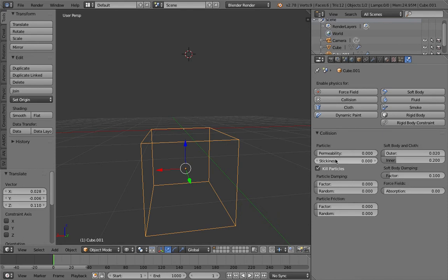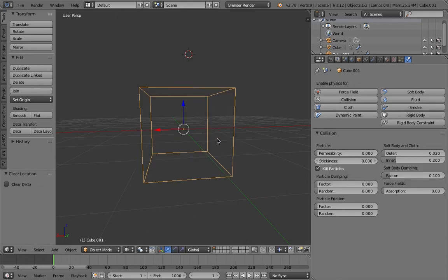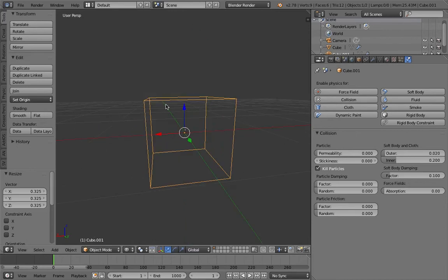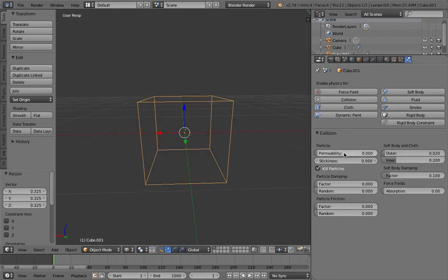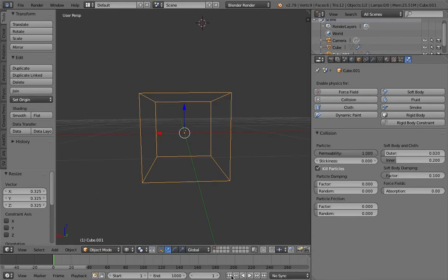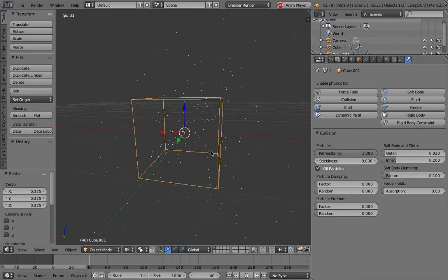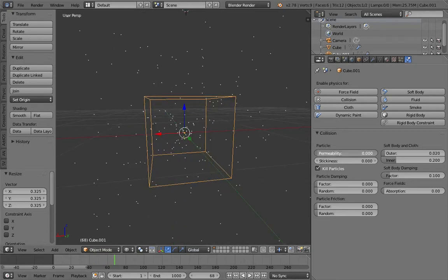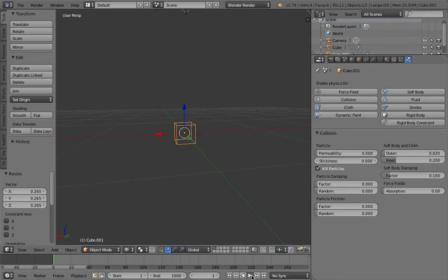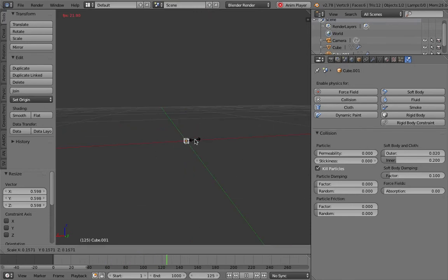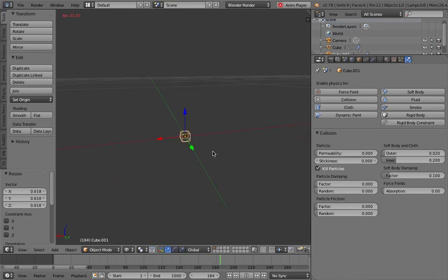And there's also something called permeability, the chance that particles will pass through the mesh. If we put the particles inside this box that kills the particles, with a permeability of 100%, what's gonna happen? Particles pass through. But if you turn this to 0, you'll see particles just kind of contained in that box, and they don't go out. So we can use this fact for our purpose.